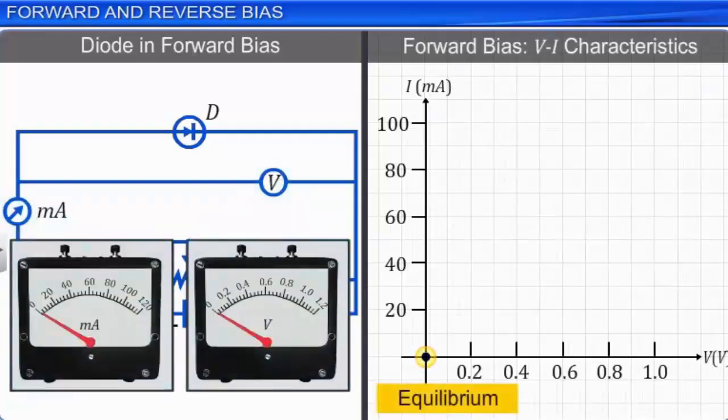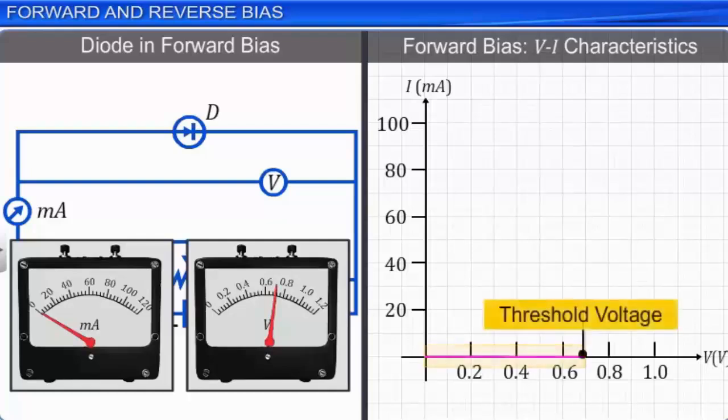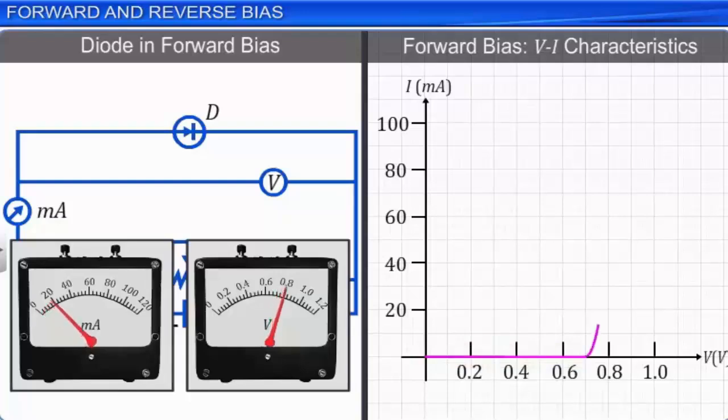The net current in a forward-biased diode remains zero or negligible until the external applied voltage reaches a certain threshold value. Beyond the threshold value, the net current in a forward-biased diode increases rapidly for small increases in the externally applied voltage. If the current increases beyond the rated value, the diode can get damaged unless it is protected. The current I in the circuit changes non-linearly with the applied potential difference, and hence the diode is said to be non-ohmic in nature.